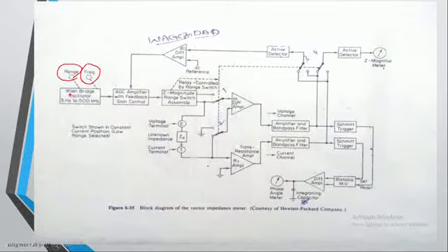Here we have the Wien bridge oscillator, which is sitting inside our vector impedance meter, for generating the required frequency signal. For generating the required frequency signal, we use this particular oscillator. After that we have the accurate gain controller, which is an amplifier with a feedback gain control.